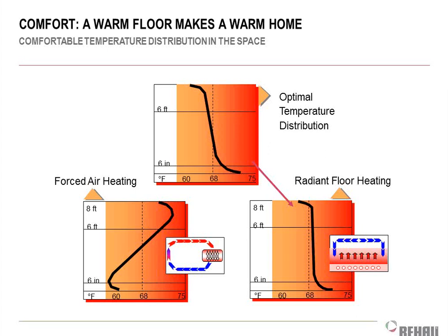But most of the people I talk to that have radiant heating in their houses, including some of my coworkers here, most of them keep it between 62 and 67 degrees on their radiant stat. So on average, you could say it's like 3 or 4 degrees cooler that you keep your radiant system than your air-based system, because you got the radiant effect warming up your body and not just the air warming up your body.